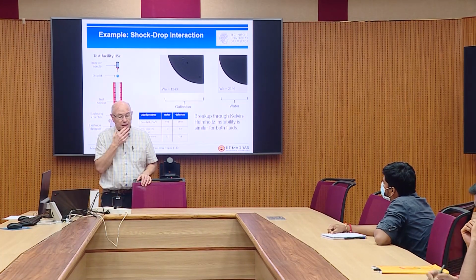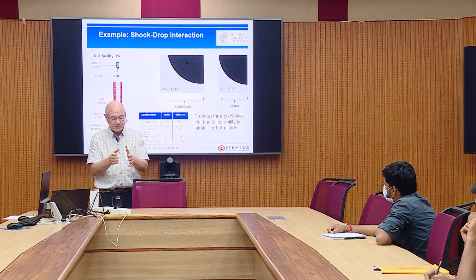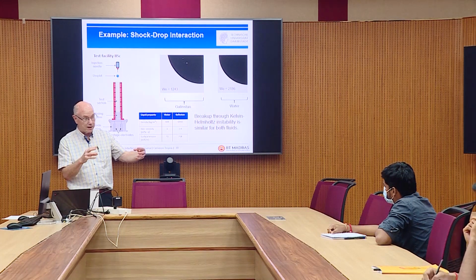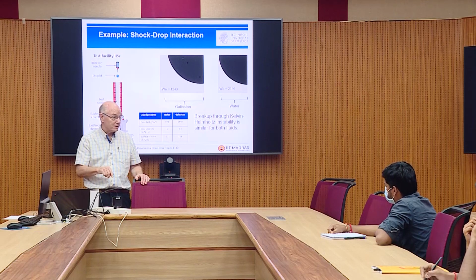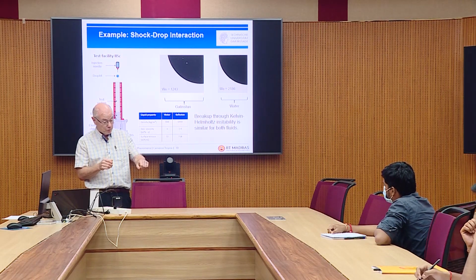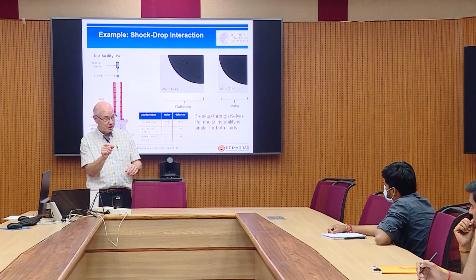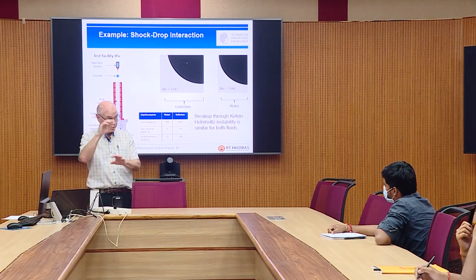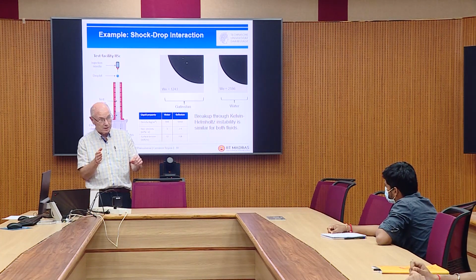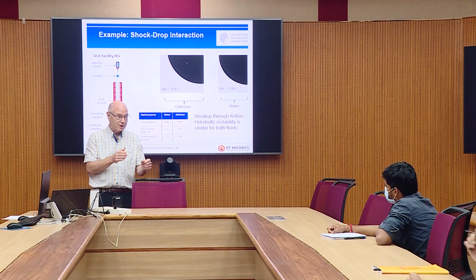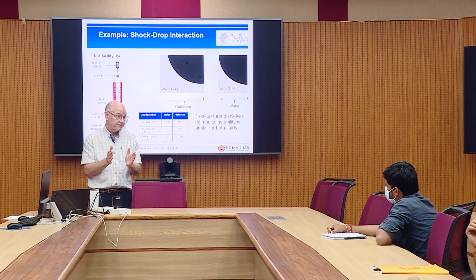And normally, when we're using the drop generators, we always have a backlighting camera on it, so we can also see how regular everything is, because it's a drop chain that comes out. And then we can change the frequency of the disturbance, and we can see the drops changing a little bit, and of course the distance between them. It's stable between here and here, and if we go too high or too low, then it becomes unstable. So there's a range in which it will still work.